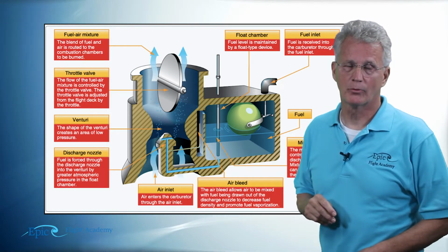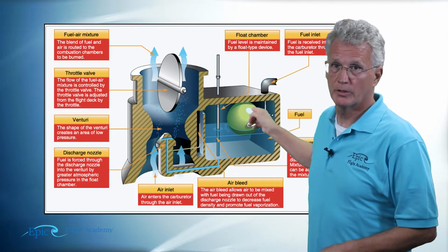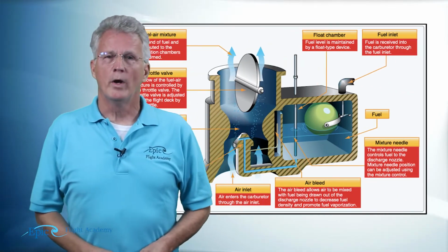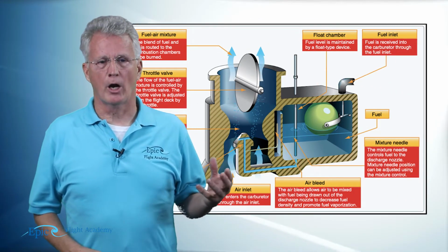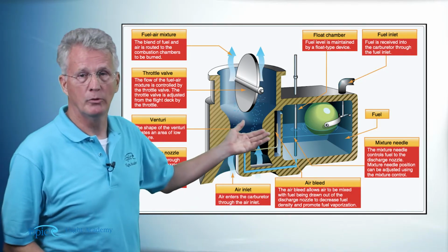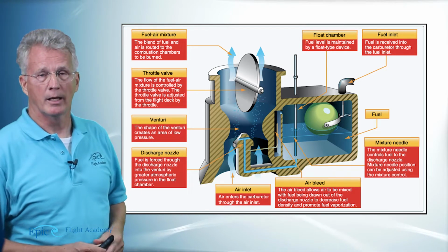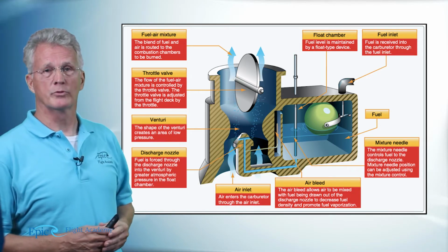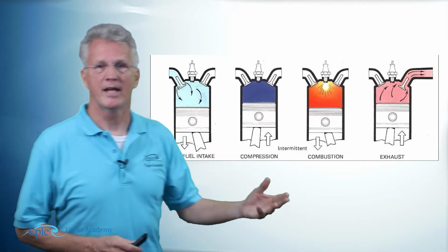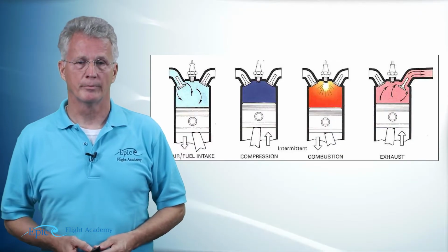That's why we pointed out the throttle and the mixture. The throttle is controlling this big throttle valve, and the mixture is controlling this needle valve. When that fuel and air are mixed in this Venturi, they are sent to each cylinder in my engine. And last time, remember we talked about the 4-stroke cycle. In the intake cycle, that's what it's intaking, that fuel-air mix from this carburetor.